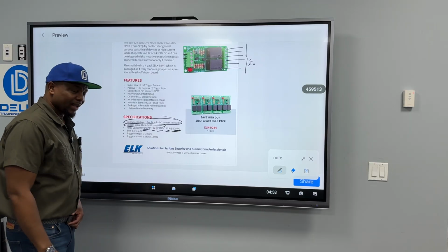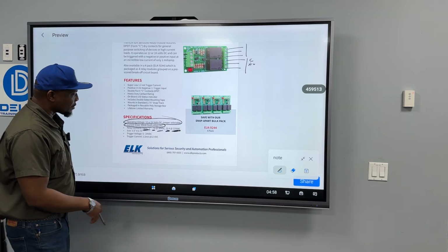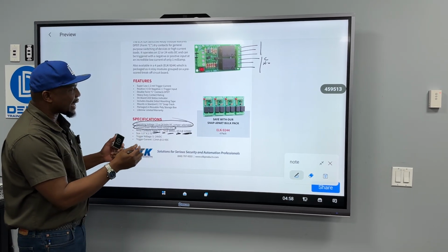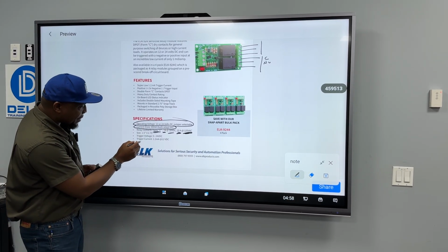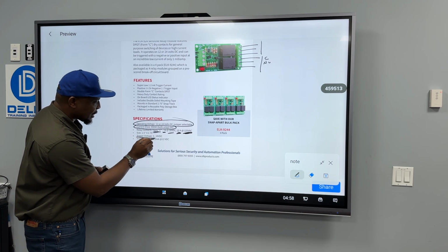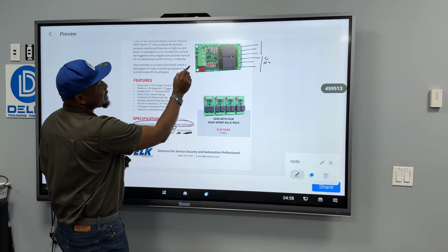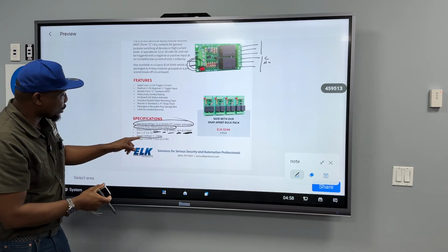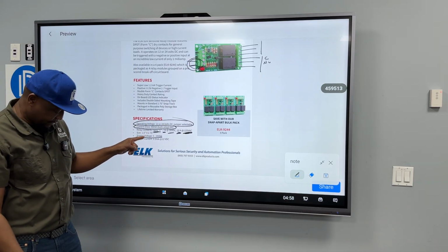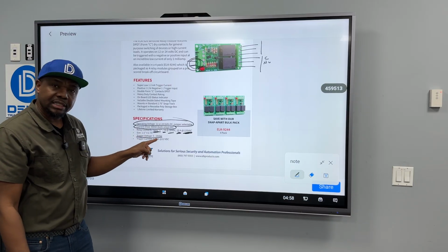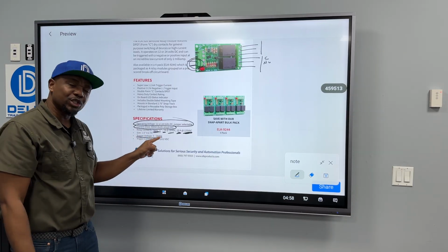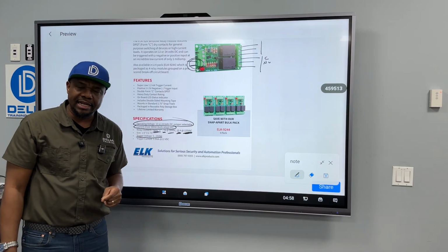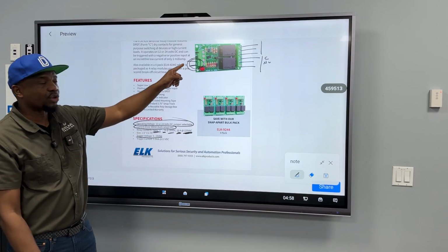Okay, so that was Nathan for you. So the data sheet is very important to show you all that. Now, this is also very important, the trigger voltage. The voltage I'm supposed to apply on the trigger portion of this, it's going to tell me. I can use anything from 5 volts DC all the way to 24 volts. So in this way, I know not to apply 30 volts to it because it's going to destroy it outright.